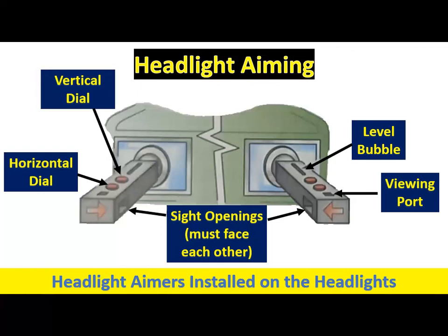Install fender covers over the vehicle body in the work area. Then select the proper headlight aimer adapter for the headlights being aligned. These adapters must fit over the aiming pads on the headlights.